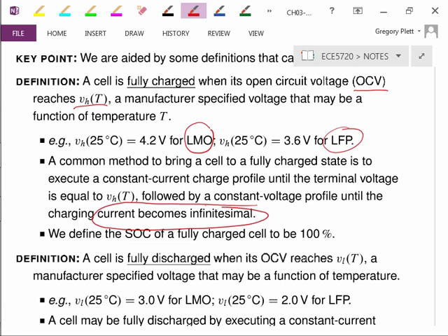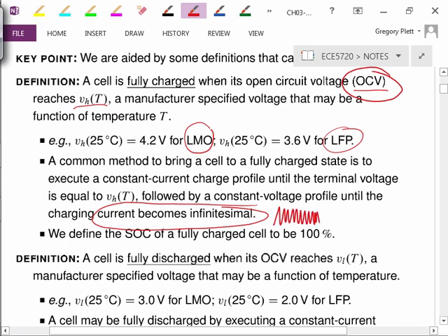If you don't consider it negligible, if you really need to be able to combat this hysteresis to truly achieve open circuit voltage equal to your maximum voltage, then you will need to execute some kind of dithering back and forth of the voltage around this Vmax set point to try to get that hysteresis loop to collapse to zero. And the dithering we talked about in chapter 2 of the last course is able to accomplish that in my experience.